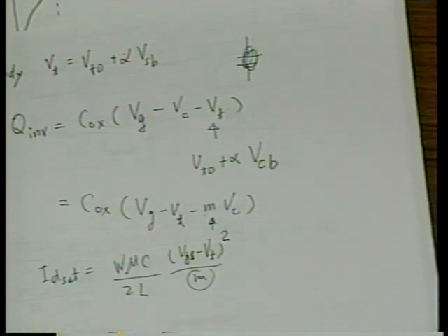Because we have a back gate, when the channel potential rises, there will be some decrease of the channel charge as a result of decrease of the voltage across the top capacitor between the channel and top gate. There's also a decrease of the channel charge because of the increase of, let's say, the voltage between the inversion layer and the bottom capacitor electrode, which is the body.